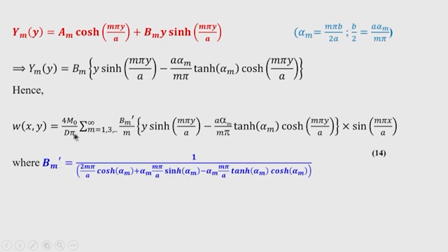So, the deflection series is completely known now for the edge moments which are symmetrically distributed on the two opposite edges. That means two opposite edges have equal magnitude of moment, if the moment is uniformly distributed, or of an equal nature. That means it is trying to sag the plate in this case.